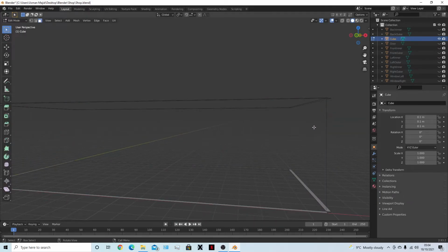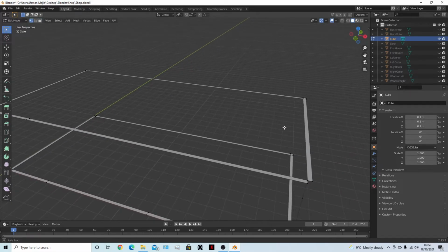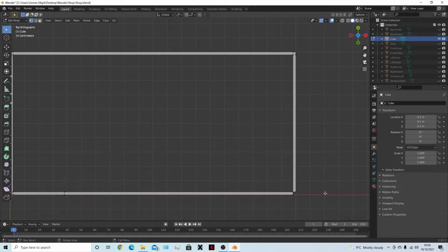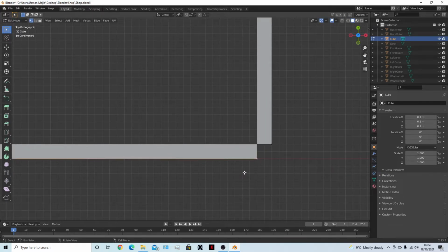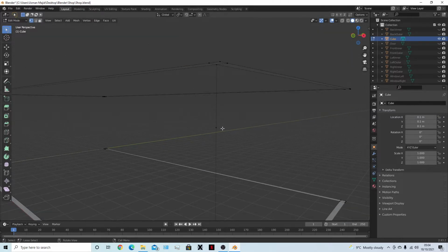Let's select this. Now what we can do is, I think, just delete, maybe. So 7, go into top view, select this edge, E, what's going on here? Crap. So press W to, I think that was E, drag these two units to 0.2, select these two, press F, select these 4, press F, so that we've got the face.